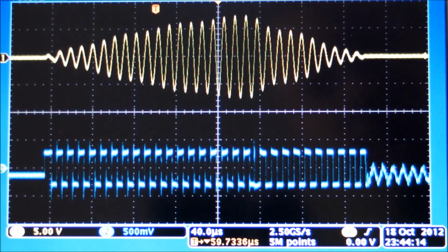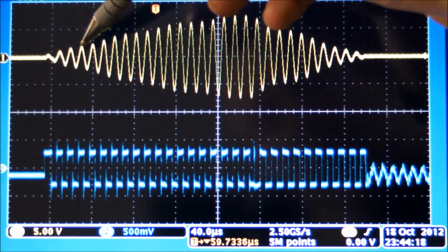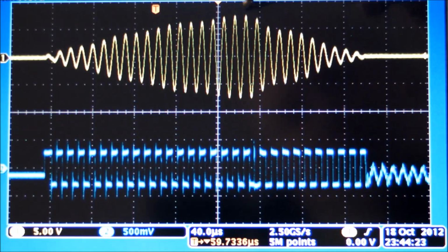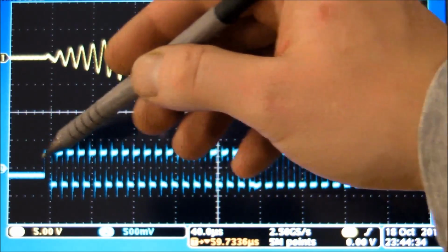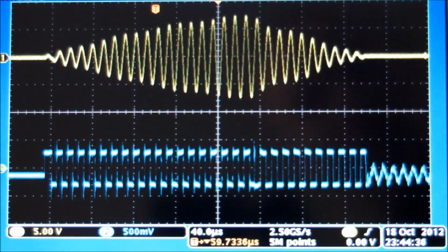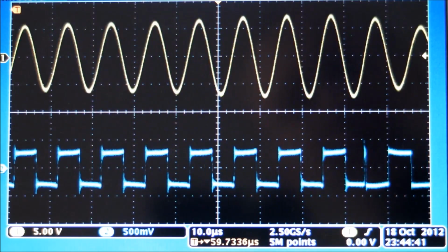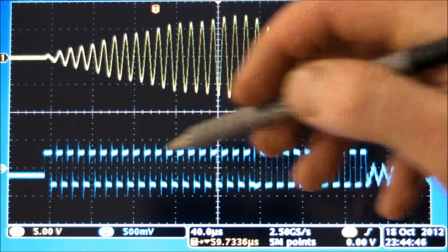Look at that. Now this is much better. Here you can see this is the primary current at 50 amps per division, starts at 0 to 200 microseconds, builds up, and then dies down as the switching turns off right here, and you can see it's much closer to a square wave than with the previous high voltage probe setup. Look at that. That's what I want to see. Just a single clean square wave.